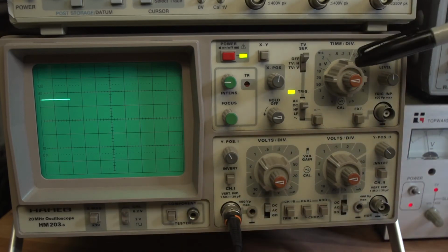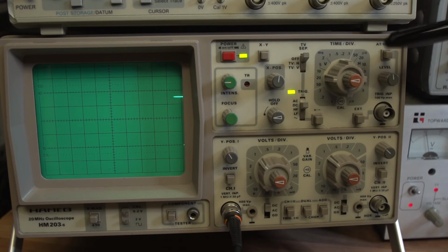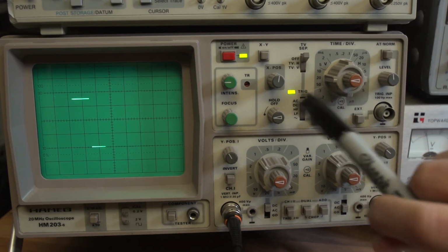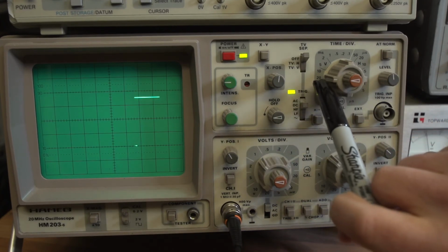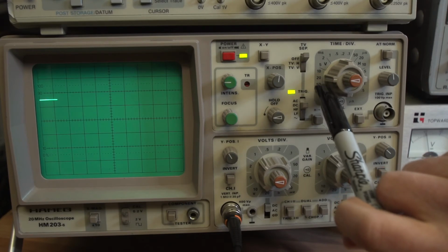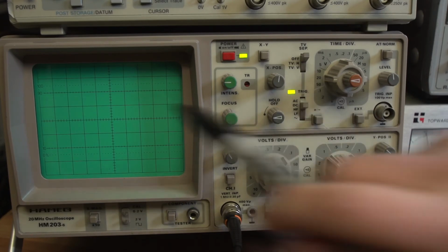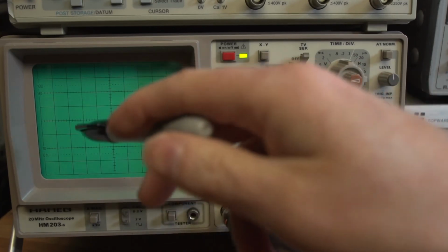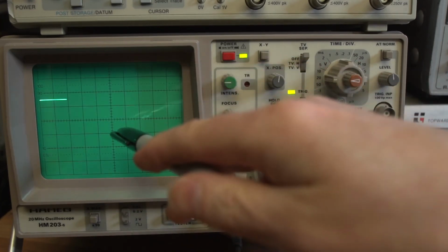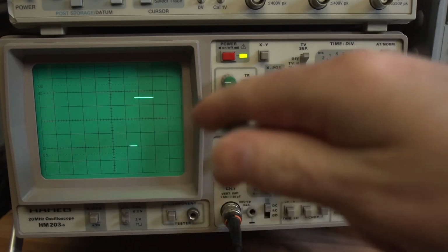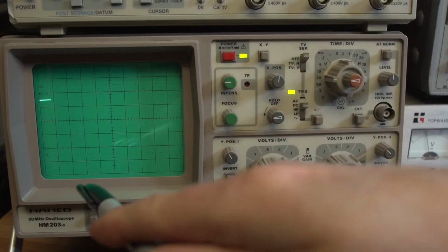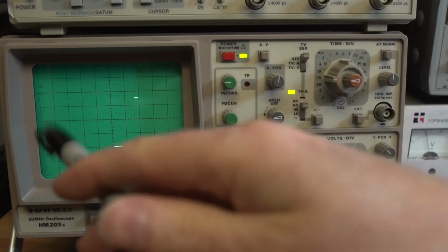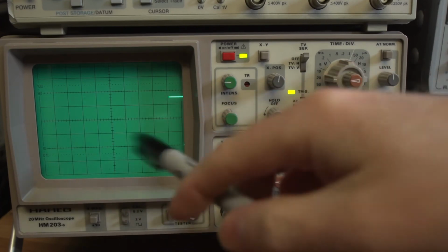Okay, well again we look at the time base control, and at the moment it's set to, don't know if you can see that or not, 20 milliseconds per division. So it's 20 milliseconds for every division. Now remember what we said before, you want a complete cycle. You don't want half a cycle or 2 cycles, you just want 1 complete cycle. And the cycle from start to end is where it starts to repeat again.